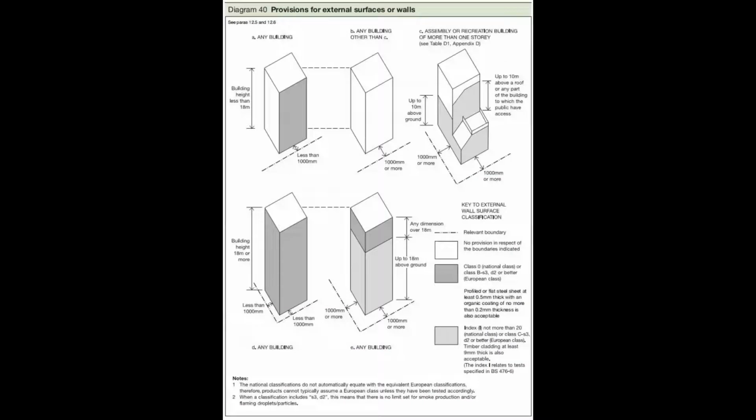The building regulations break down information into quite clear diagrammatic and text form. They're advisory documents, and in some instances there'll be occasions where one can question this and one can come to another agreement. Now, this is a process where in England you can appoint an approved inspector. It's different in Scotland. That approved inspector doesn't exist. An approved inspector is somebody who can sign off building regulations as opposed to the local authority.